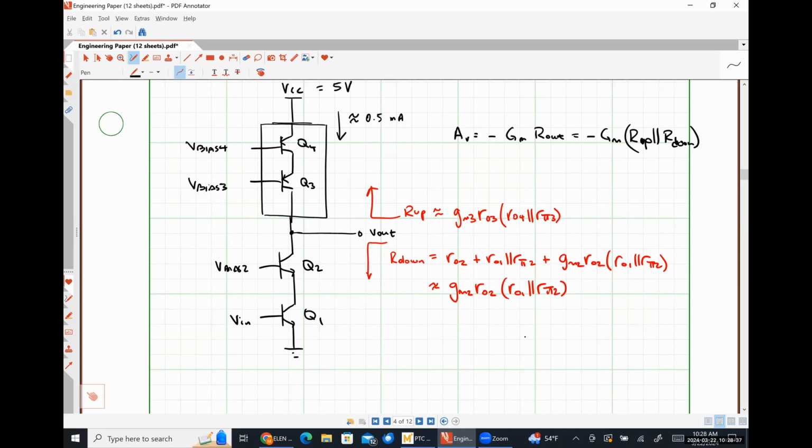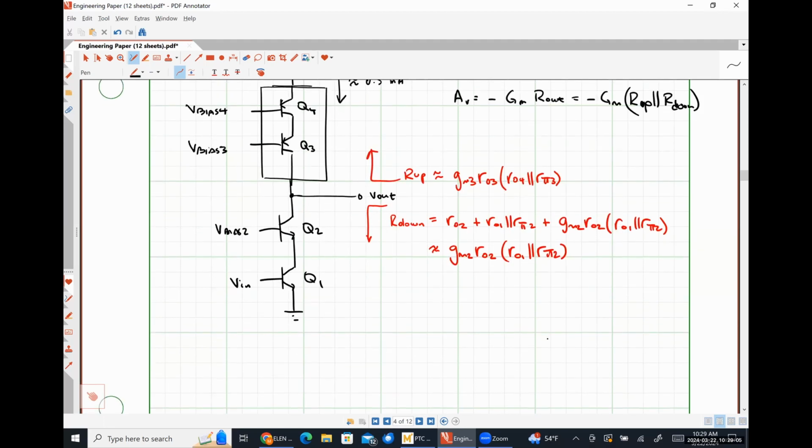That's the beauty of the small signal resistance of a transistor. Is that it's a small signal resistance, not a large signal resistance. Whereas a physical resistor exhibits the exact same resistance in both our large signal model and our small signal model, which means we get large DC voltage drops across them, eating up all of our headroom. We're talking about specifically integrated circuit type things where we don't have the luxury of using 36-volt power supplies and all of that kind of jazz.